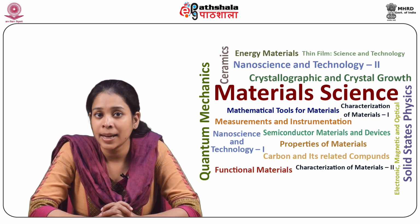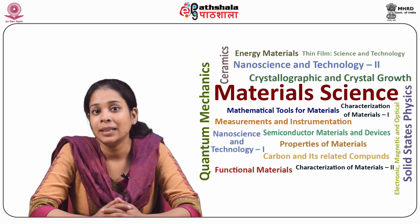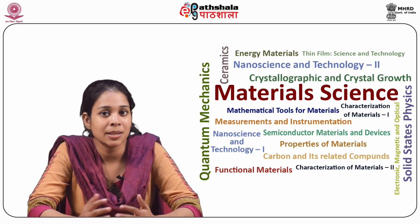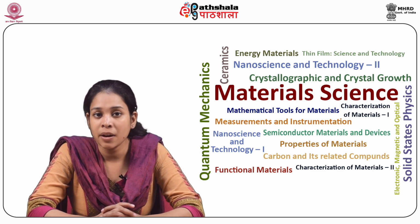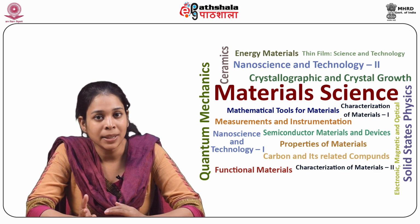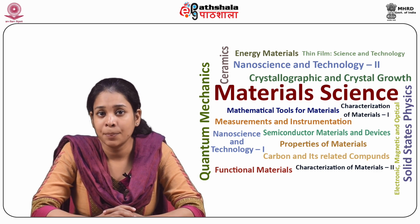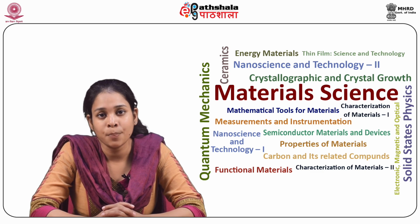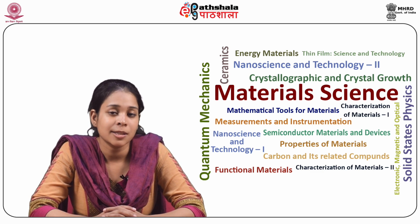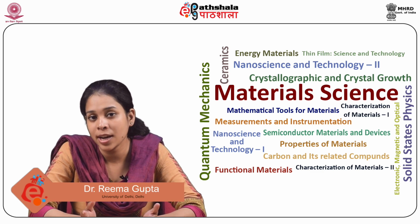We have discussed the ionic bonding, and in ionic bonding the bond energy is larger and it has larger alpha values. For example, in case of MgO, it is 1000 kilojoules per mole. Whereas in covalent bonding, the bond energy is variable. For diamond it is large and for bismuth it is small. Next is the metallic bonding which we have discussed. In this bonding the bond energy is variable. It is large for tungsten, small for mercury and moderate for aluminium. It varies over a large range.